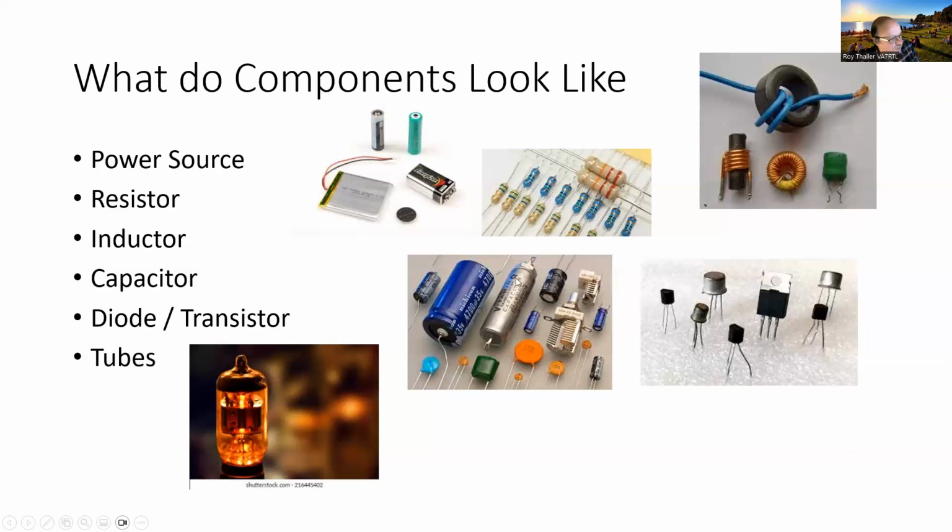Here's a pass-through capacitor. If you're trying to separate one part of a circuit from another part, you may actually put the power supply or a signal through one of these capacitors, feed-through capacitors. They're not used that often, but this is an example of one.